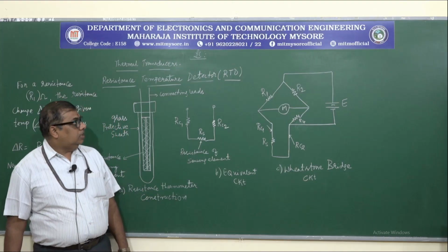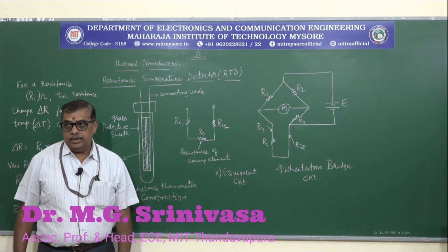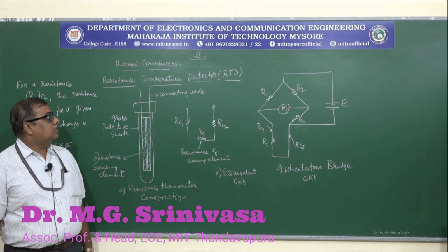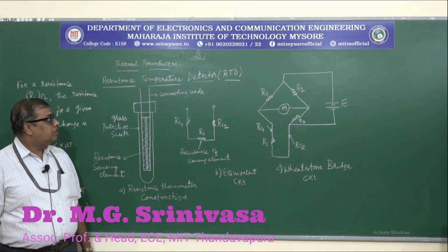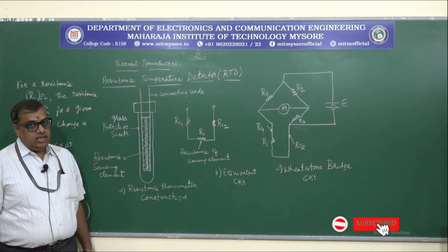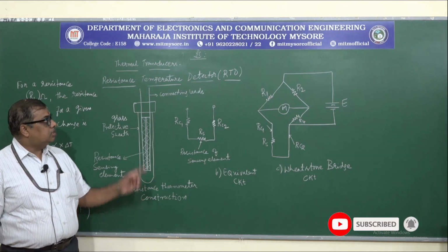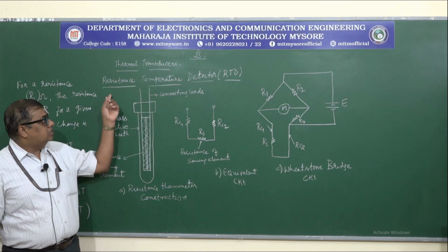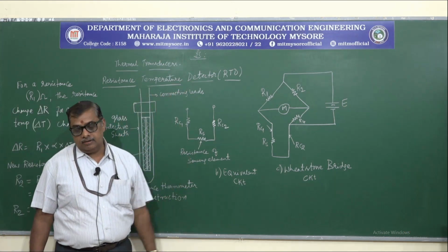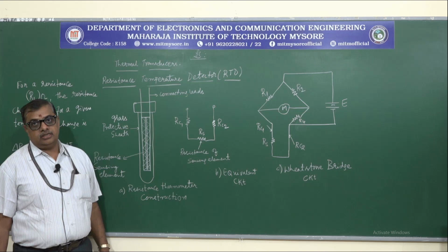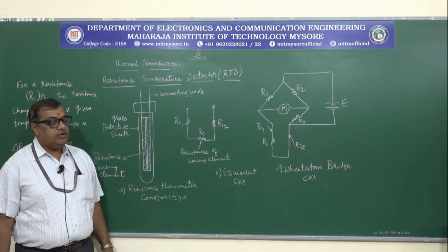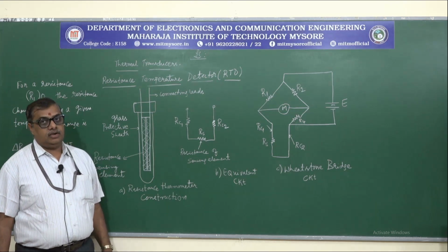Hello, very good morning. In this class, let us continue with the thermal transducers. There are basically three types of thermal transducers. One is called the RTD, the resistance temperature detector, the second one is called the thermistor, and the third one is called the thermocouple transducer.